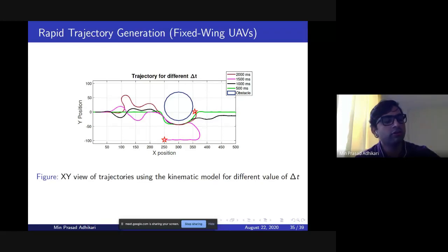For a lot of other processes, unless they customize it for the specific application using the general solvers, the solution time is really high. Even for this NLP, without customization, the solution time is definitely higher. So you may not be able to solve even within that 200 millisecond of solution time, I mean, 500 millisecond of sampling time. I'm not sure about other approaches. According to my research, though I didn't do the best literature review, it seems that those are computationally intensive.